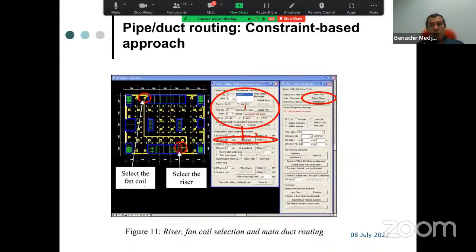Then in this case, we know that looking at the position of the starting and ending point, we can't have one segment, we can't have two segments of our duct. Then we straightforwardly start to generate a solution with three segments that will allow the system to very quickly test the solution with three straight segments. Then the response time will be quite low. And obviously we will use a non-overlapping constraint to make sure that the pipe doesn't pass through any obstacle.